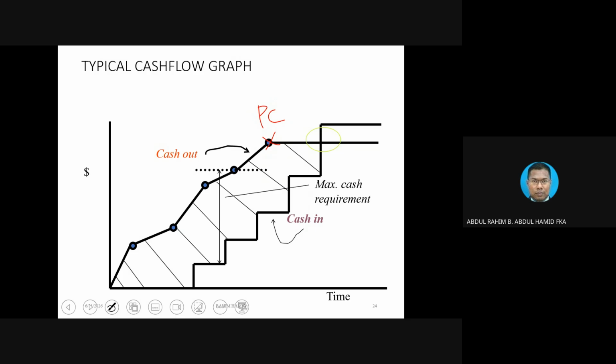Then the contractor will go through the defect liability period. The contractor has gone from the construction site because they already cleared the site, and they are going to another project which might not be nearby. And then during the defect liability period, whatever defect, the contractor has to rectify. And the client will call the contractor, and then supposedly the contractor has to come immediately. But since they are not there, maybe they have really moved to another state, it will take them time to come and repair. And sometimes they don't even come to repair. That is the issue. So the client needs to act fast.